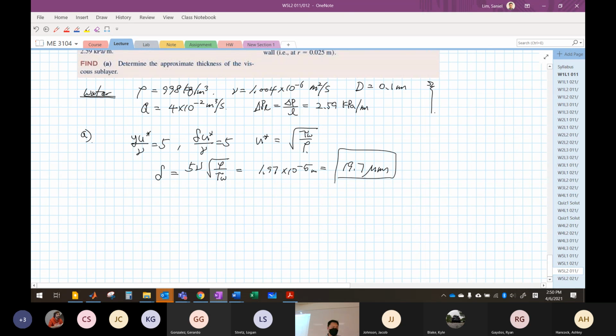All right. So according to the graph, you can use those macro-size measurements, flow rate, density, viscosity of the water, and the diameter of the pipe. Then you can find the thickness of the sublayer, which is fairly small, right? So only 20 micrometers. In the case of our air duct lab, it's going to be a really, really thin layer. So it's pretty much not measurable using a centimeter-size pitot-static tube, right? That's what you can expect. If you measure it, it's probably wrong.